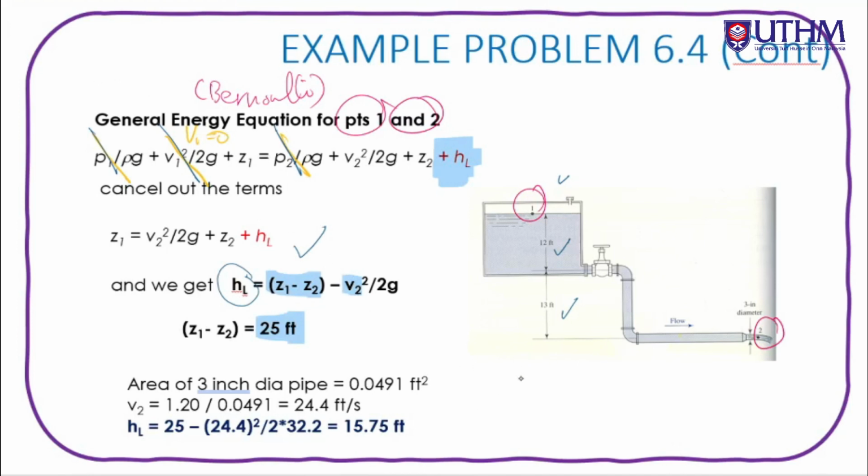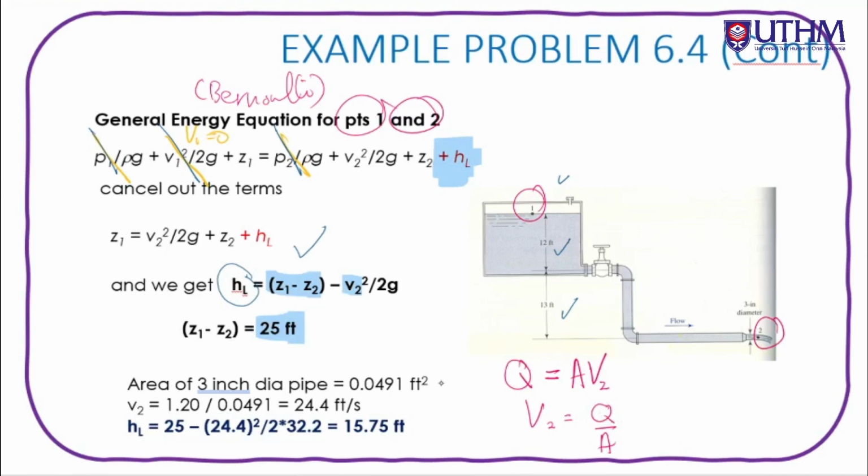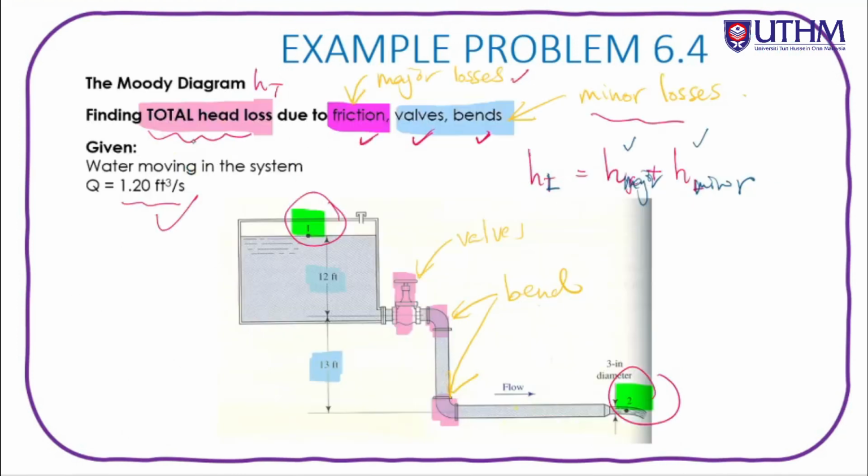So based on last time, we learned continuity, Q equals A times V, and the flow rate equals the area of the pipe times the velocity. Then V2 is equivalent to Q over A, given that Q is 1.2 feet cubed per second. We substitute and then divide by the area. Area, since in the question it said...